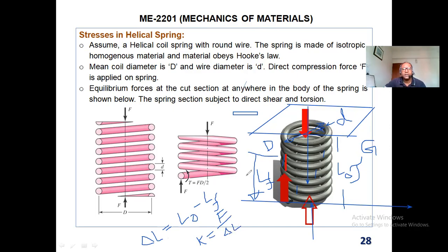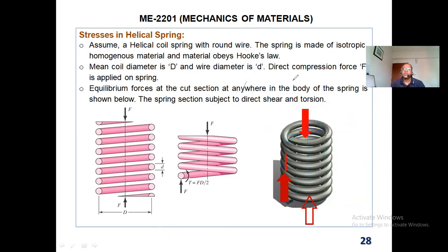Now, our purpose is to find how the spring fails, how much shear stress works there if you apply load F. That we need to derive as a formula. So if I cut right over here this spring, this wire, then we'll make the free body. If I like to draw by hand sketching this spring, say right over here, it has failed.